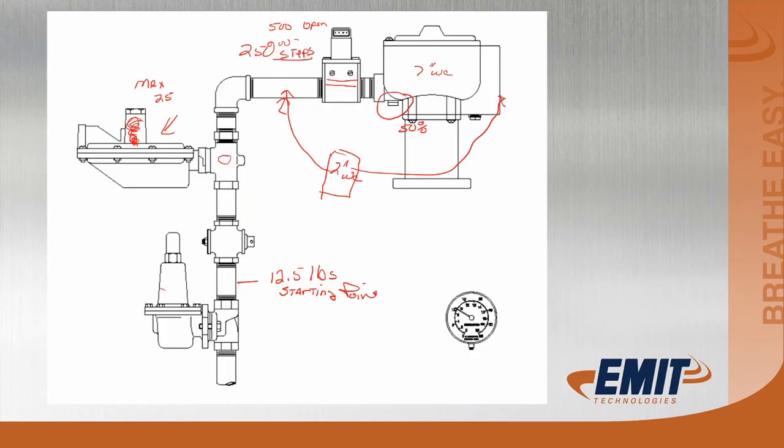Okay, so if we need more fuel, you always go to the little Joe and increase the pressure. If you reach 25 pounds, that may be the max on this regulator. You always want to read the data tag up here on the regulator. Once you reach the max for that regulator, and you're not able to maintain 5 inches of water column under a load, that means the orifice in this regulator is not big enough. That means you need to increase the orifice size. Okay?